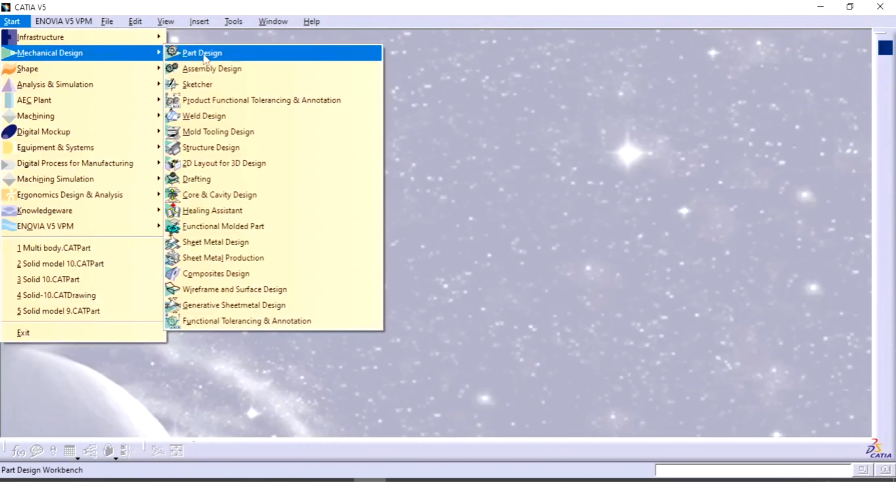Like this. Then double click on the constraint, right click, click on one line, click on the other line, right click, allow symmetry line, this one. For this one as well, make it symmetry. Okay, done.